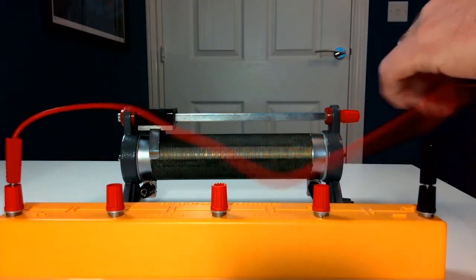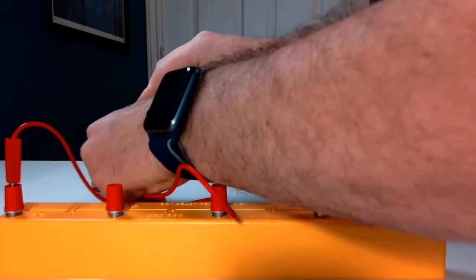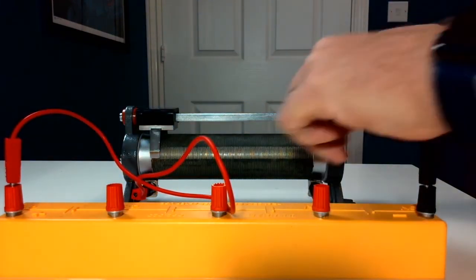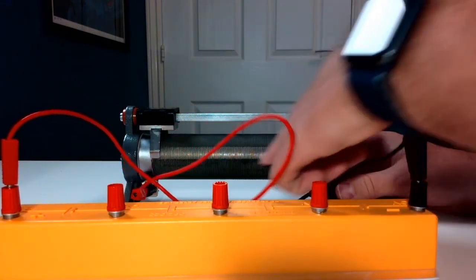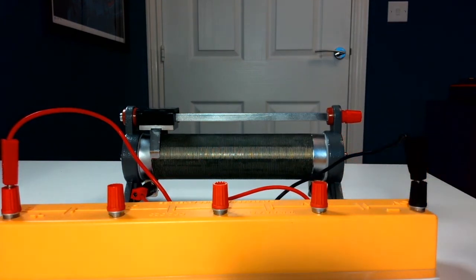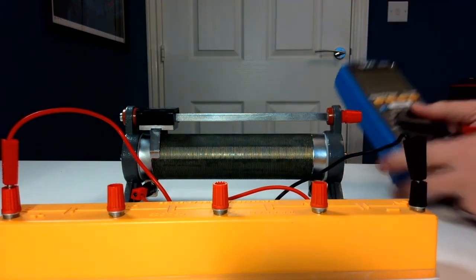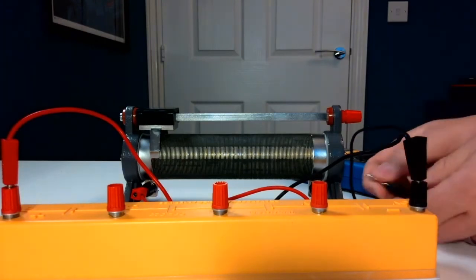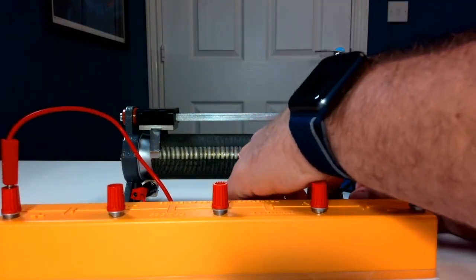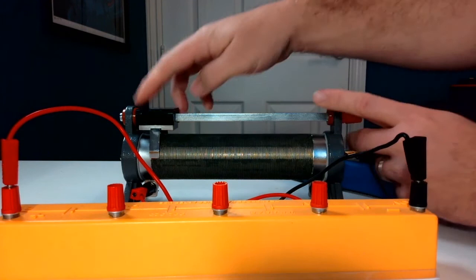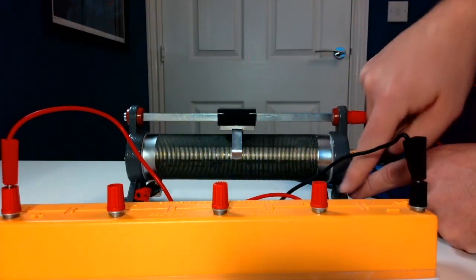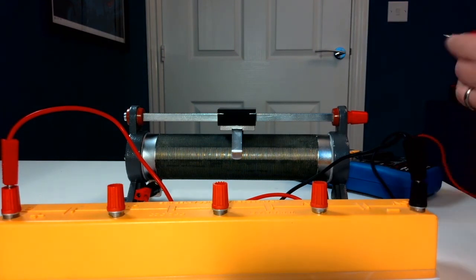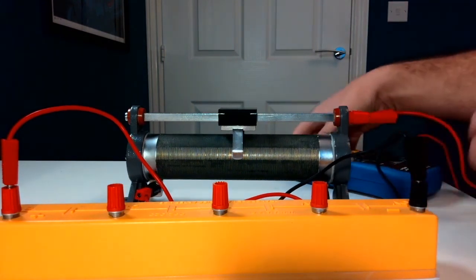So let's try now attaching this rheostat to a power supply, or in fact in this case some batteries. So it should be approximately 6 volts, the potential difference across the full resistor at the bottom. And if we then attach a multimeter here so that we can read the voltage, the potential difference across from here down to here, we should be able to vary the potential difference.